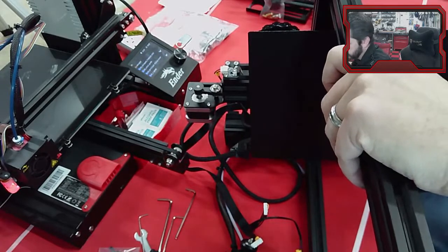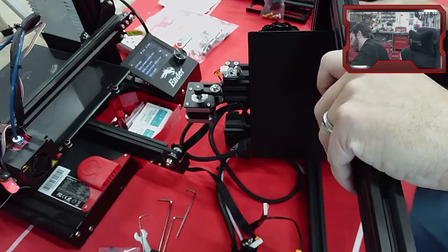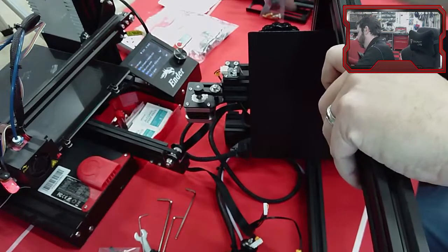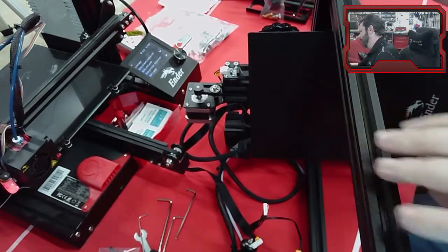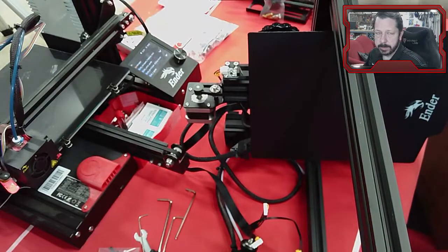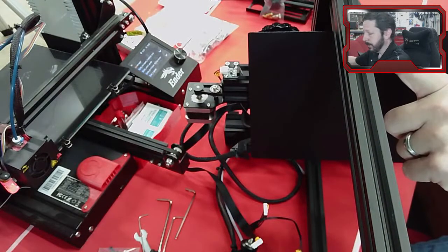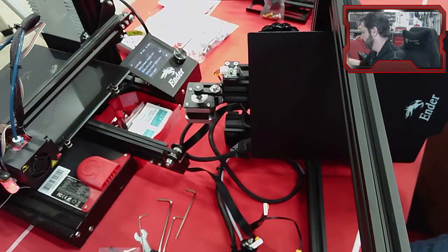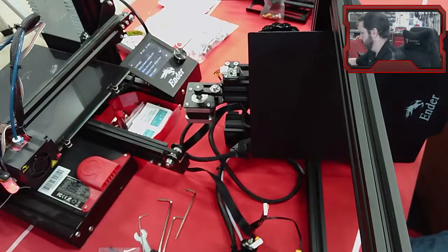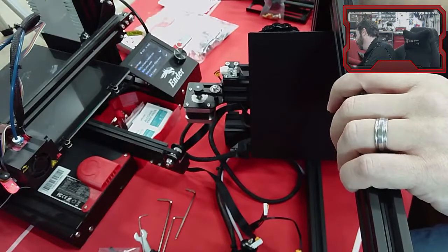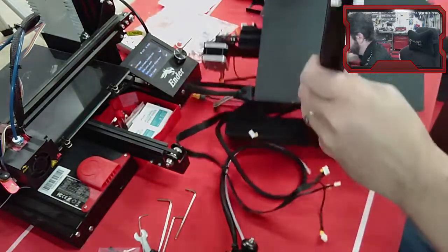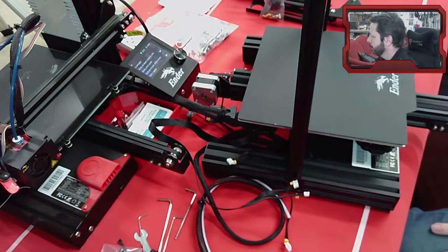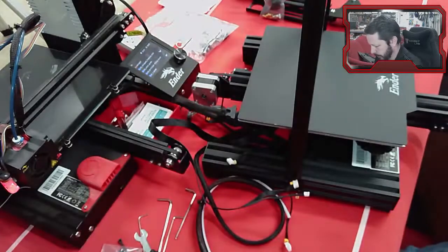These particular instructions are, oh, you know what? I didn't check. Yeah, these had washers already on the bolts, so they're fine. Oh, when you're tightening these, you do want it tight, but you don't necessarily want to strip anything. This is aluminum, so it is possible that you over tighten and strip the threads that are threaded into the ends of the aluminum. So don't overdo it for sure, because that's going to be a hard fix to rethread, or you basically would have to get a larger diameter bolt and rethread the threads in there, which is not going to be a simple thing to do.